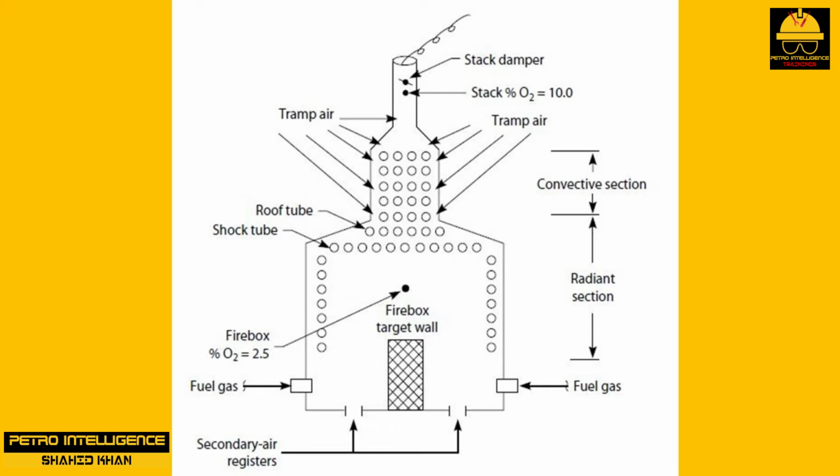However, an oxygen analyzer in the stack or convective section is really useful only in operations if there is also an oxygen analyzer in the firebox. In such instances it could be used to trend air leaks across the convective section. Never ever use an online analyzer for technical analysis or test work.